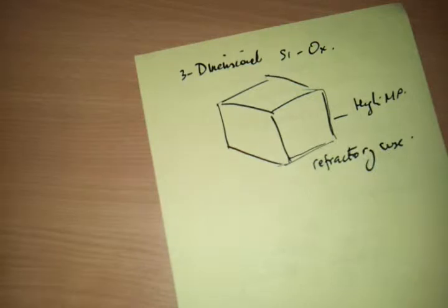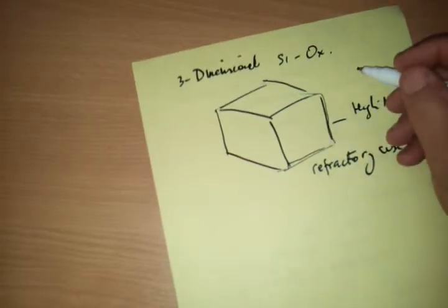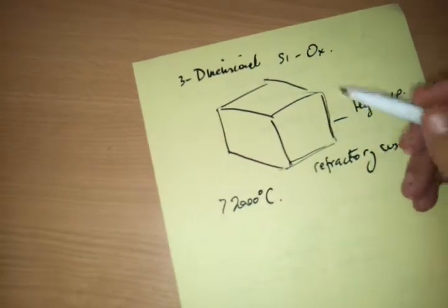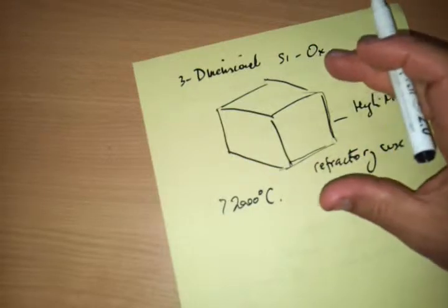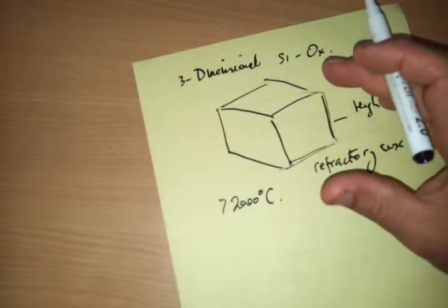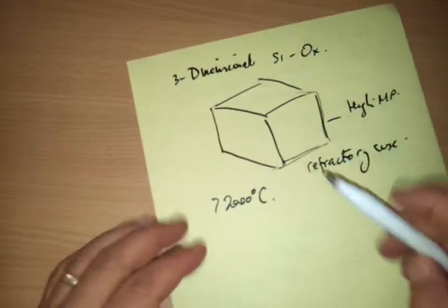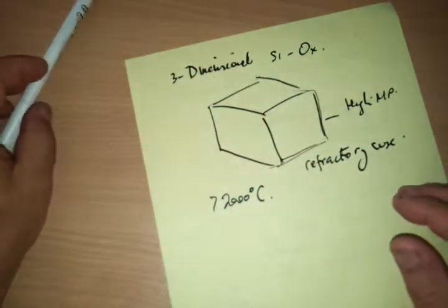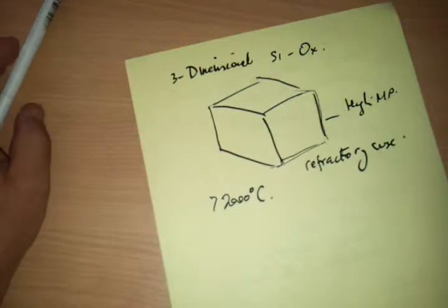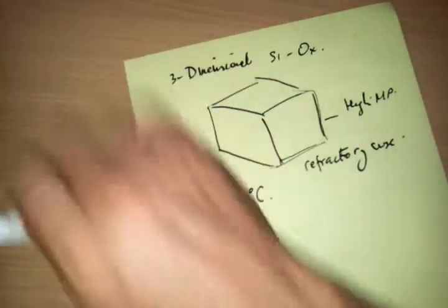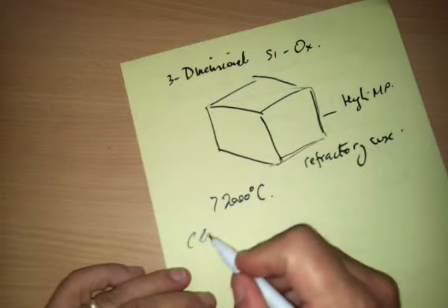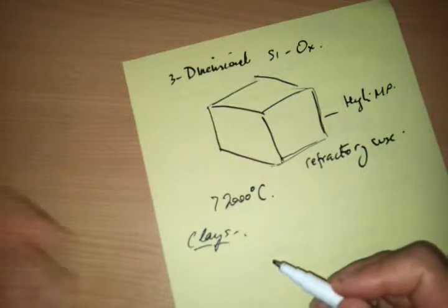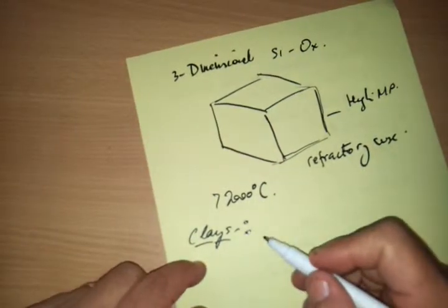So these refractory furnaces, the heat resistance can be up to over 2000 degrees for these silicon oxygen combinations when they're in a three-dimensional lattice like that. Now, also these clays, these silicates that are used in clays, more in the sheet form, have a lot of great uses, and clays can come in lots of forms. The clay, in its normal state, occurring in the ground, usually has water involved. These are clays. They have water involved, and when that water is dried out, the clay becomes hard.